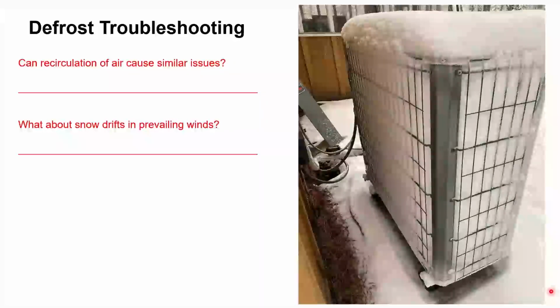I also went on a job up in Central Washington, and they were complaining that their utility bills were high. I get out there, and they had dug the outdoor unit out about a foot all the way around it. The top of the unit was about 3.5 feet off of ground level. The snow was 4 foot deep.